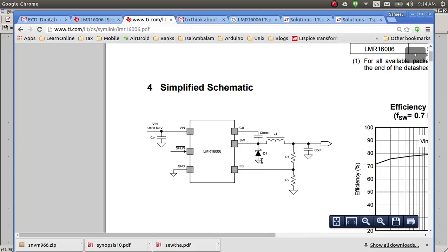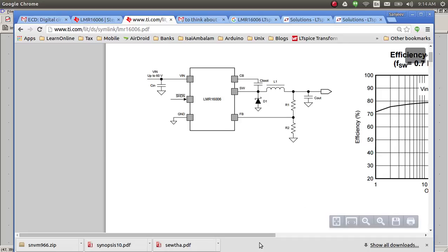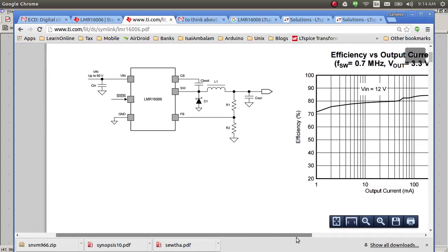It has a Zener diode that fixes the voltage. Then it needs the inductor for the buck boost functionality. That's an external inductor. And then this is a typical usage. This is your C out, this is the output going out, and then the output has a resistor divider which goes to the feedback. So that's probably how you determine what kind of output voltage you want by changing the resistors.